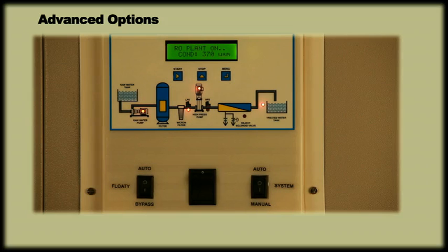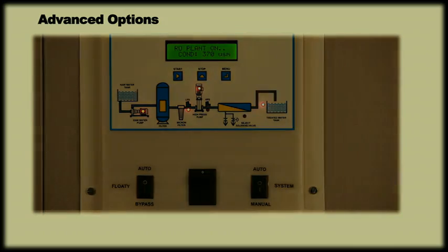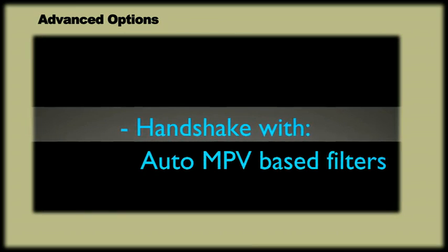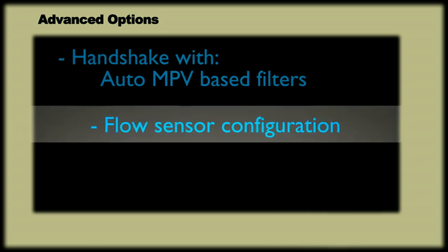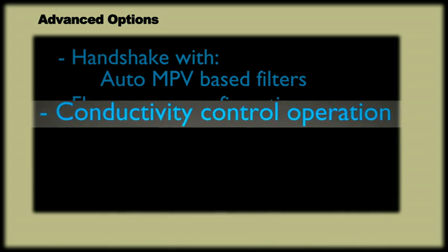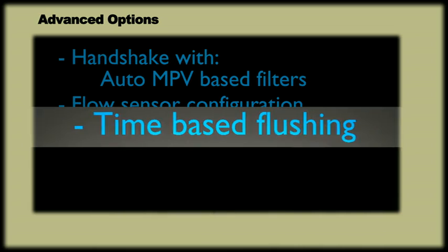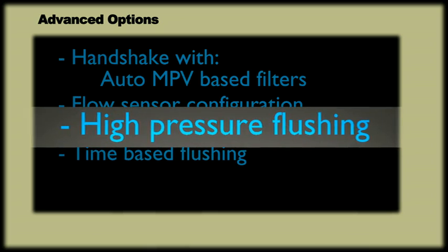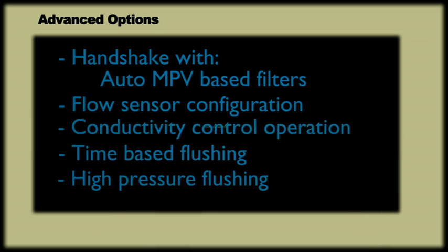Advanced options. The panel has following advanced features which can be enabled based on site or customer requirement. Handshake with auto multiport valve based filters. Flow sensor configuration. Conductivity control operation. Time based flushing. High pressure flushing. Dry run protection.